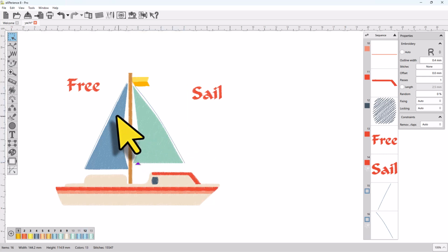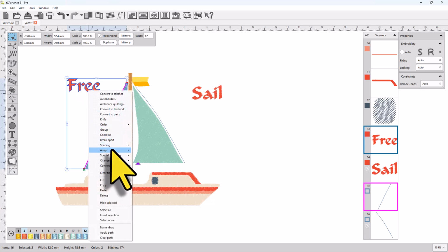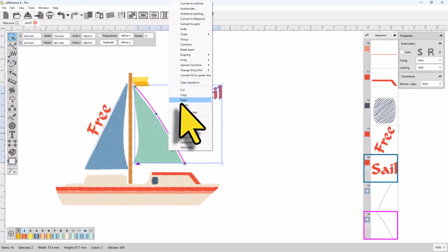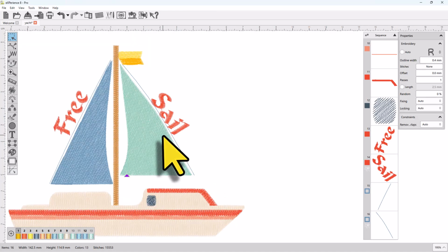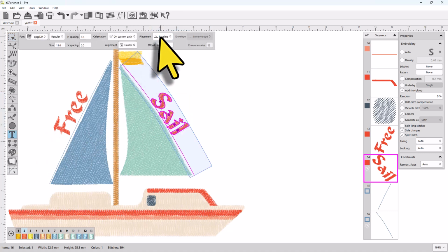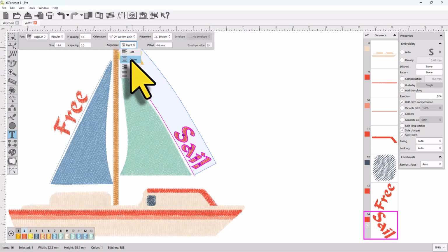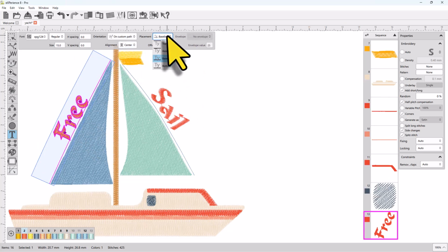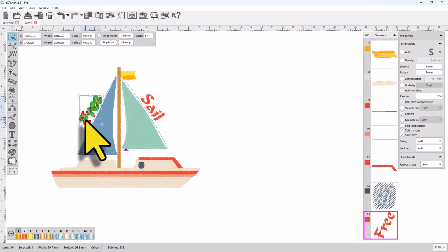Now you can use any of these lines as a custom path. Select a custom path together with the text part, right-click, and from the appearing menu, select the Apply Path option. The custom path we created has been applied to the text. The same applies to the other custom path. See how this one goes downwards as we drew the path? Now you can start the Text tool to edit the text normally and customize all options. To remove the path, simply right-click and choose Clear Path.